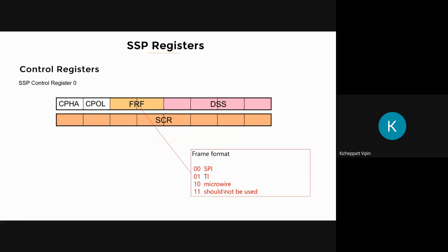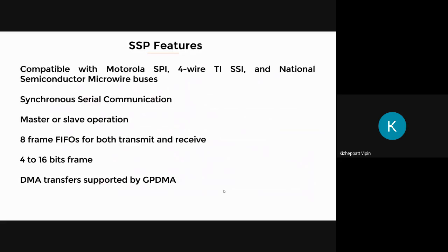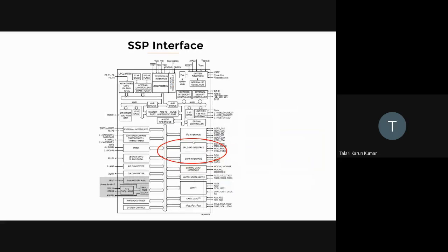Maybe saved for future. Let me ask you a question now. How many SPI interfaces can the LPC2378 have? Maximum number of SPI interfaces. 3. Oh, okay, good. How did you find 3? Can you tell me the 3 ones? SPI is as usual 1. SPI 0 and 1 is there. Okay. SSP 0 and another SSP 1 is there.